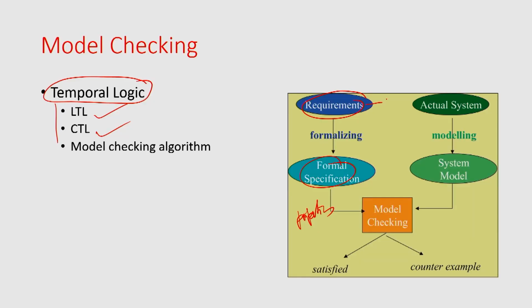So from here you implement, right? You have the synthesis tool and you implement, you have the actual system, and then you model that system also as maybe a finite state machine, right? So you need a system model, you cannot just take the actual implementation. And then with these properties P and this model, you just check whether the model satisfies the properties or not, right?